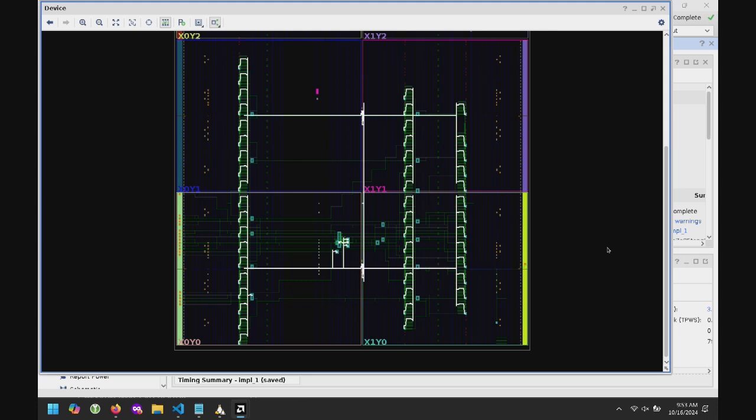Let's think about why for a second. So in CMOS, when does CMOS require power? Or when does CMOS take up the most power? Yeah, exactly, switching. Generally, if CMOS is stable, we can almost assume that it's taking up 0 power. But the second that it switches, the act of charging up the wire that it's connected to, that is what takes the most power. So in CMOS, switching is the thing that takes the most power, okay?